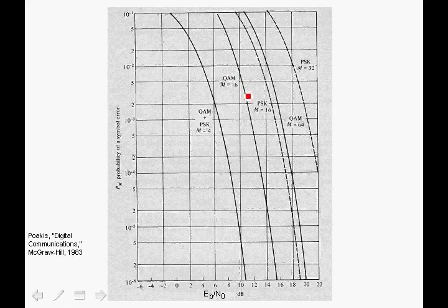Only when the signal-to-noise ratio is increased, then we can switch over to a higher throughput 16 QAM type modulation. So this illustrates also the necessity for rate scaling when we have cases of high SNR, and when the SNR is low, we have to downshift to, for example, QPSK or BPSK in order to achieve reliable communication over the link.